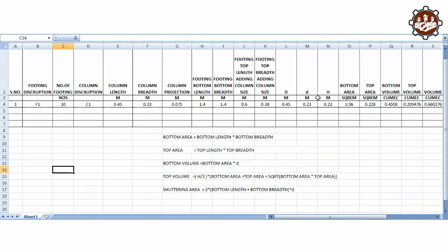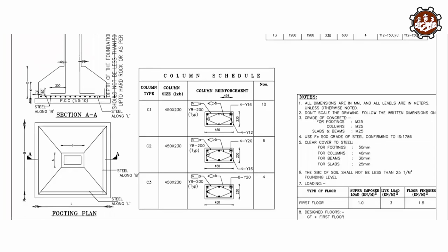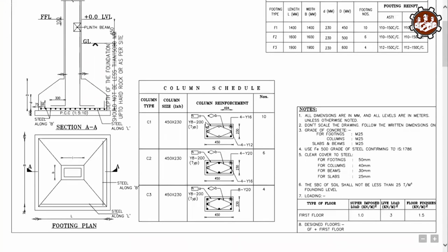Today, I am here for the discussion of isolated footing from live project drawings. In this session, I will explain how to study and analyze the structural drawings of isolated footing, how to take up the quantity from the drawings, and how to calculate the quantity of concrete work and shuttering area in an Excel sheet in very detail.